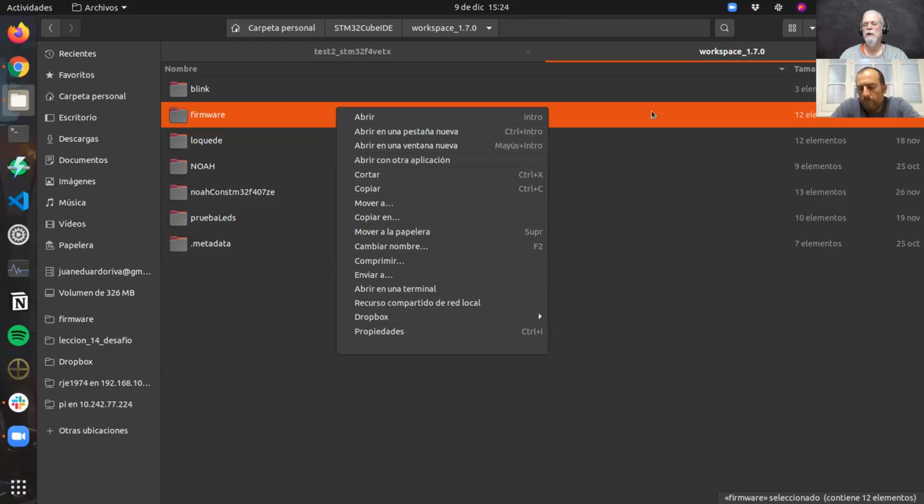on that one to change it, you click on the, over on the left, it will say firmware.iot, double click on that, it'll open your MX, and then go through and do the steps of changing the compatible processor like we did. And then I don't know if you have to save it or whatever, but then your project should be ready to go once you change that processor name. Then go ahead and try to, and at that, don't say, well, I guess you could say generate code, because it's smart enough to know if they wrote the code correctly. They got these little blocks that say don't overwrite your existing code.